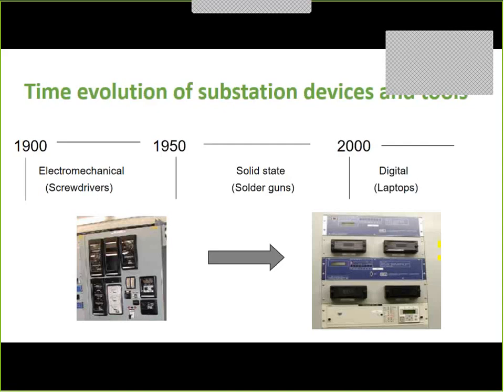And the way it was explained to me was if everybody is operating close to their maximum capacity and you lose one source, then all the others are now over capacity, and one by one they all trip out. Am I making sense? Yeah, that does make sense. It would probably be a violation of our security criteria, which means you have to be able to survive contingencies. So it shouldn't happen, but I can see that in some countries it could. And you're right, that's a very good point.